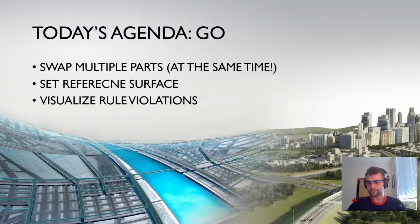First, swap multiple parts. A big feature with Project Explorer is that with Gravity Networks you no longer have to swap parts one by one. You can swap parts through the entire network, multiple parts at the same time. Second, set reference surface, so you can set the reference surface of that pipe network. In some cases you might want to lay the pipe network out without a reference surface and then set that surface afterwards. It can all be done within Project Explorer. And third, visualizing those rule violations so they're no longer buried at the structure and part level anymore.